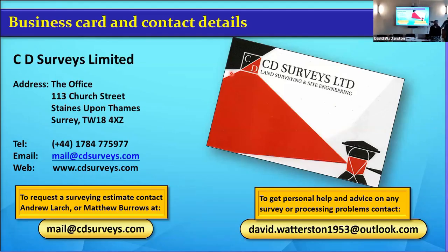What this used to do was go down to the benchmark. So you go from, as I said, the benchmarks are probably 200 meters apart. So you get one benchmark level, and then to prove that, you come back. You can check that your readings are all right. What we used to do was, if that compares fine, to prove it, you go to a third one. When you go to a third one, if all three of them match up with the results, fine. So you could only use one, but you could go change. So that's the idea of the benchmark. Once you take that benchmark out, you then level to the site.